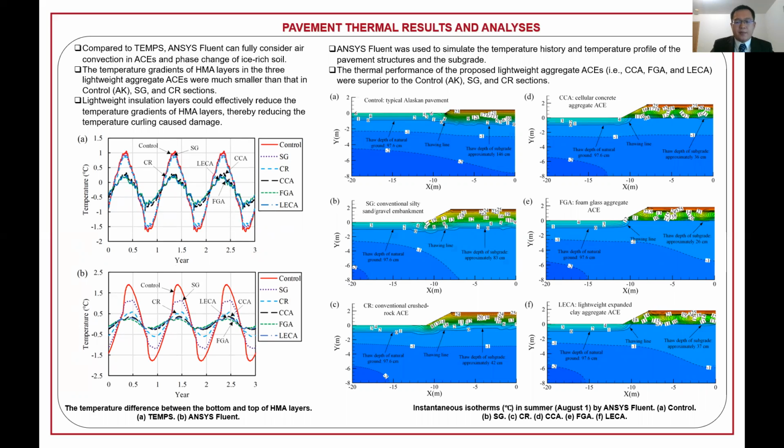In summer, the ambient temperature is higher than the subgrade soil, and the pavement structure is mainly heated from the top surface. The air density gradient is relatively stable, which allows the porous medium to function as a thermal insulation layer to prevent the subgrade soil from thawing.